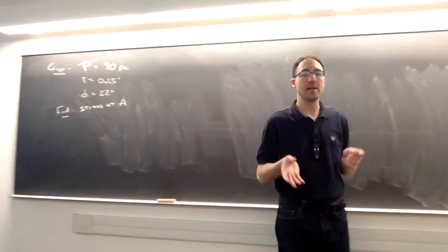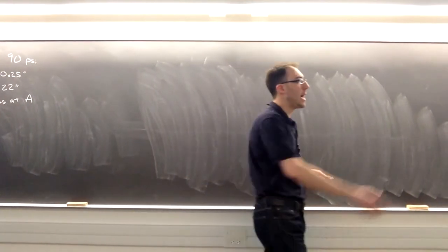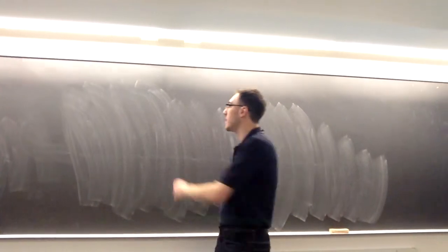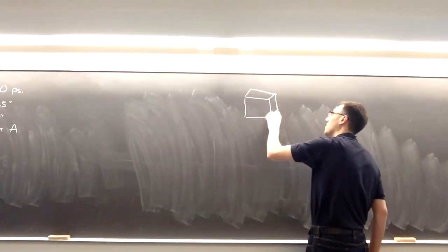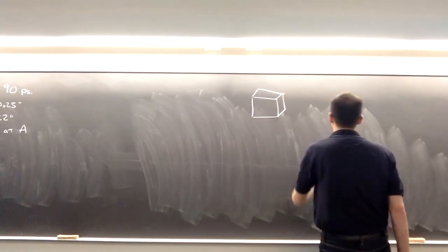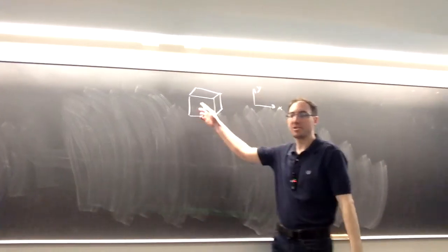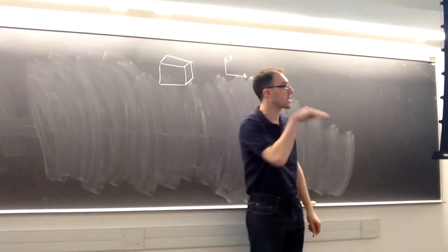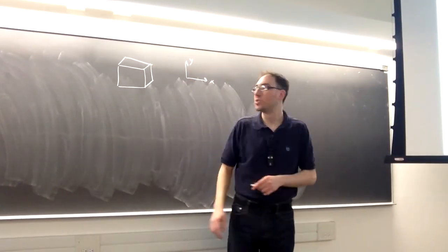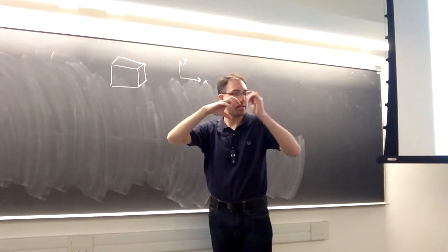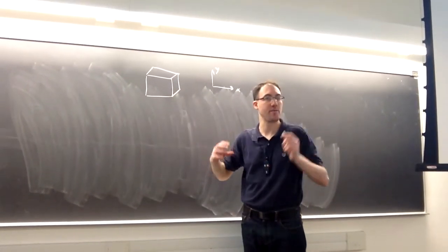Right, so to draw the stress state, I'm going to make what we call a stress cube or a stress element, and I'm going to align it with the tank. So if I assign, this will be matched to how I drew my picture. I'm going to say X is the longitudinal direction and Y is along the hoop direction here. So I want to see what are the stresses acting on this little infinitesimal piece of material, and I want to draw the correct directions for all those stresses.